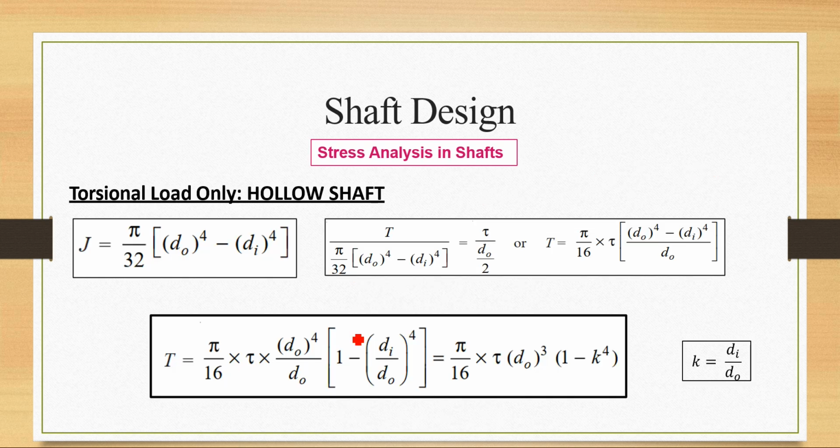But if you have a torque shaft that is hollow, generally in case of heavy vehicles, we use a propeller shaft that is hollow. A hollow shaft has the advantage of transmitting high torque as compared to a solid shaft. So the only difference from the previous formula is the outer diameter, because the hollow shaft has two diameters.